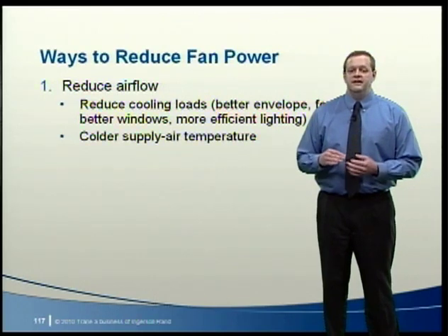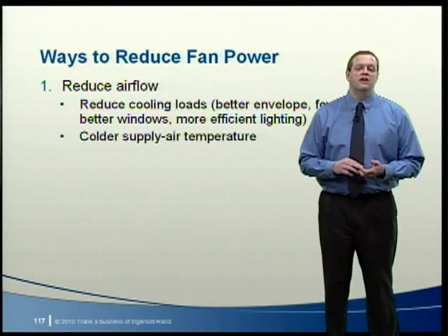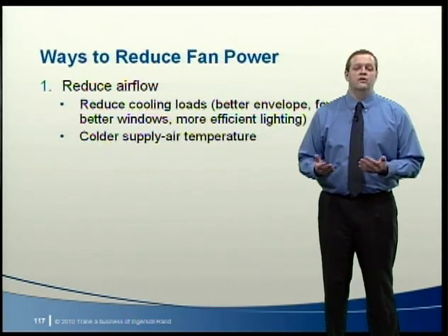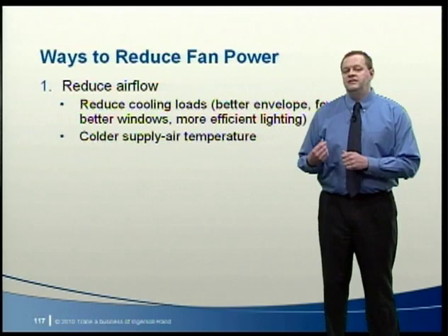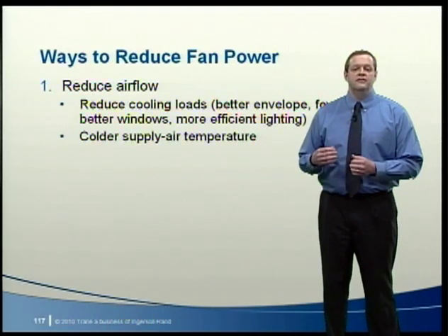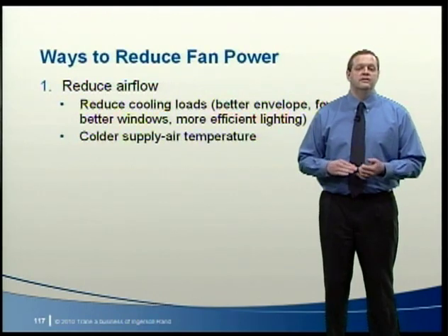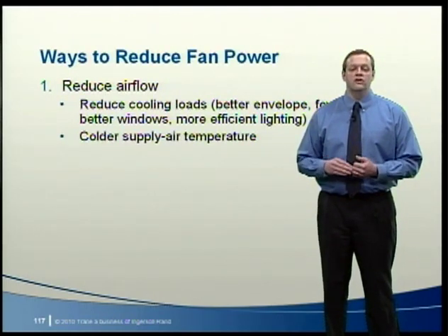If you downsize the air handling unit and ductwork so much that the airside pressure loss is the same as when you started, it will still result in less fan horsepower, but the horsepower per unit CFM might not change. So if you need help to meet the 90.1 requirements, consider keeping the air handlers and ducts a little larger, not downsizing them so much, to reduce airside pressure loss. This would then result in lower horsepower per CFM.